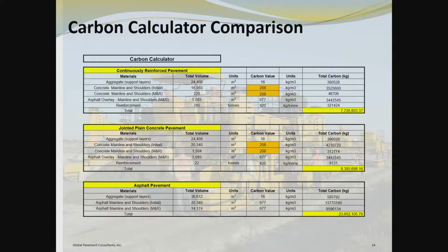So it might be cement plus fly ash, it might be cement plus slag. Both of those are the default position in the U.S. And it's not necessarily because of carbon footprint, that's just an offshoot. It is not necessarily because of economy. It's because it kills ASR reactivity and because it gives us longer lasting, better concrete at some percentage of addition.